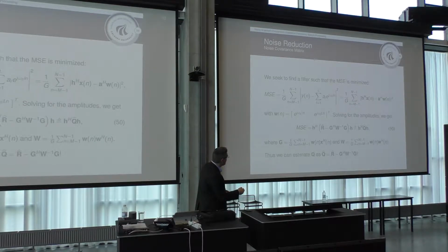And this is the covariance matrix of the observed signal. Actually, it's the sample covariance matrix of the observed signal here. And then you subtract out this thing here. If you look at what this is, you have W times X, and then W times W Hermitian transpose here. You can see that what this does is subtract out the contribution of the candidate harmonics from the sample covariance matrix. So this is actually an estimate of the noise covariance matrix.